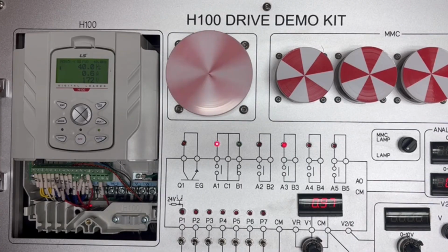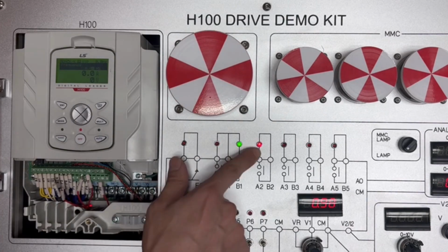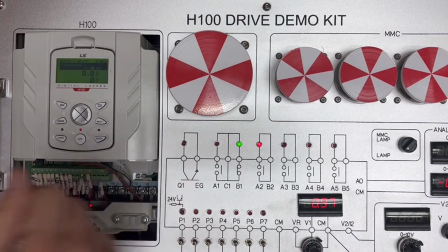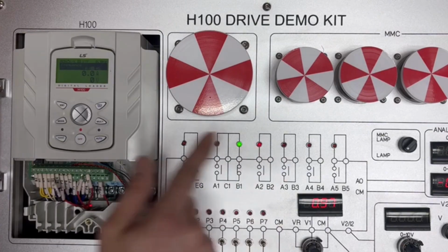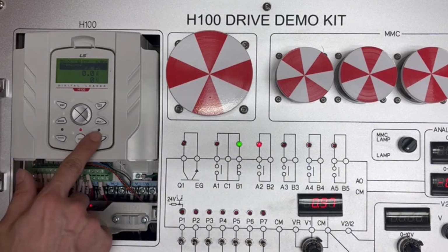So now, if I stop the inverter and it reaches the stop state, my relay 2 should be activated. I'm stopping the inverter now. As soon as the frequency drops all the way down to 0, you'll see that my relay 2 is now being activated. I'll start the inverter again. The start mode has been activated. Relay 1 must be activated, and when it reaches 40 Hz, the command frequency, relay 3 must be activated.